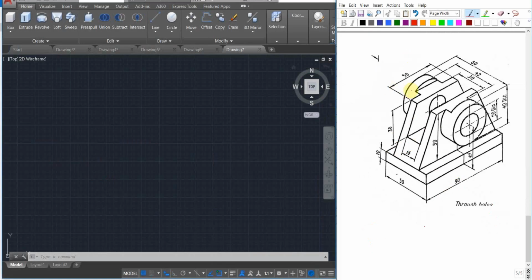So now let us consider this shape. It would seem kind of complicated, but if you try to break it down, it's going to be much simpler, right? As we agreed through this video. So one of the things, for example, that I can work on is the base. I'm just going to draw this face and extrude it by 50 millimeters, and definitely this is going to be the front, and this is going to be the left hand side of the shape, and this is going to be the top view. Make sense? So we can start with the base, then extrude it with 50. This is one of the things.